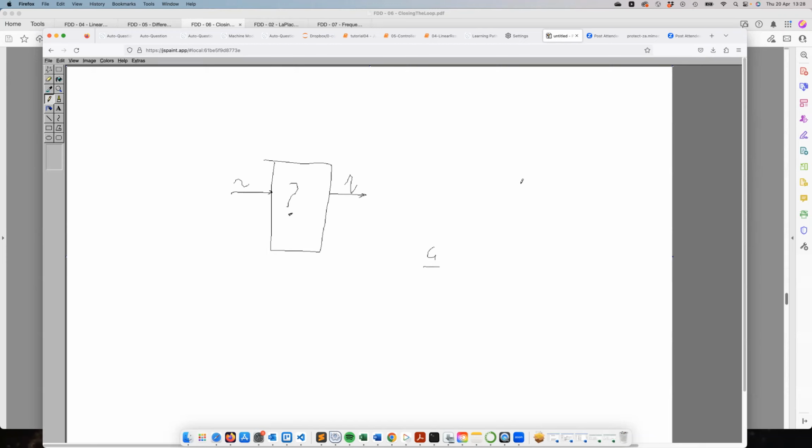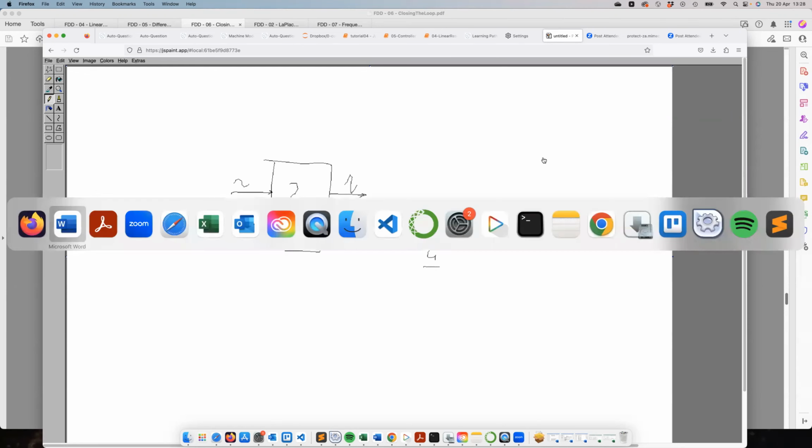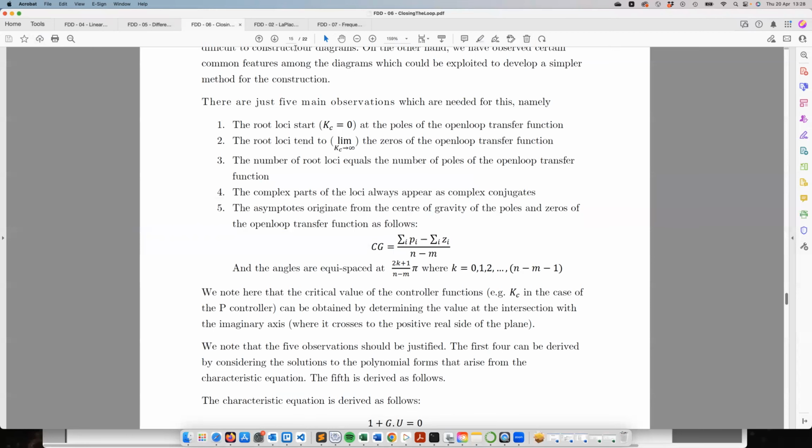In the 2 tanks case, we developed the material balances, and then we could fully describe the rate of change of the height in each tank. And we referenced that to the control variable, the input or the output, one of those. So we derived g. And what we are saying now is, is there not a way for us to directly measure g? And towards this, we have available to us the so-called basic theorem.